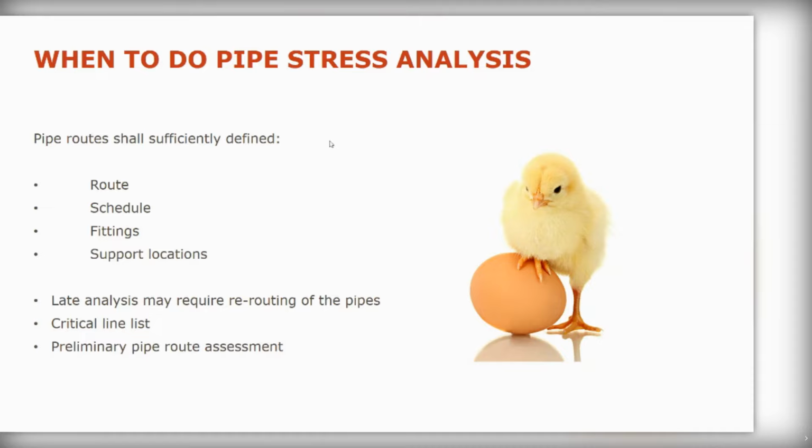Normally that means the largest pipes, pipes that are hottest, and pipes connected to pressure vessels need to be routed first. Other minor ones that can be easily rerouted, leave them till later. So move this into your project plan.